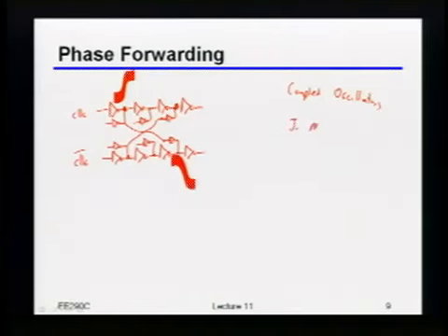This was done by a guy named John Matiadis. This was his PhD thesis. And I forget, this was back in the late 90s or so. Let me see if I actually wrote down when it was. Yeah, it was maybe even early 90s, excuse me, like maybe 91, 92. Okay? So basically what he showed was that if you took a whole bunch of different ring oscillators and coupled them in smart ways, you could essentially guarantee certain modes of overall oscillation, but get the equivalent of gate delays much, much less than a fan out of 4. Or really much, much less than what you could have done without these coupling tricks.